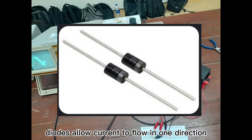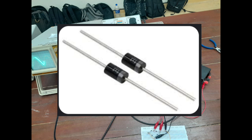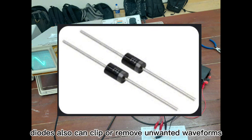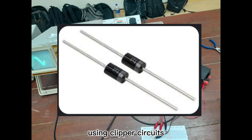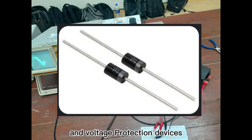In conclusion, diodes allow current to flow in one direction, which enables us to convert AC to DC in rectifiers. Diodes can also clip or remove unwanted waveforms using clipper circuits. These circuits are essential in designing power supplies, signal conditioning systems, and voltage protection devices.